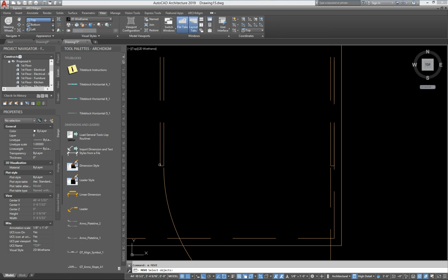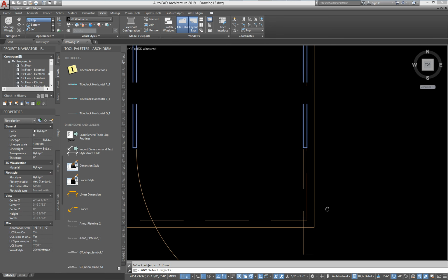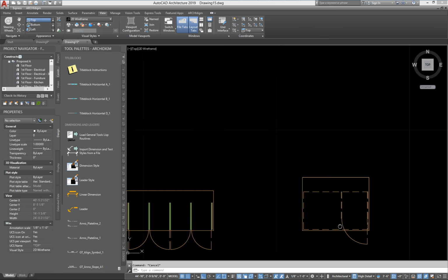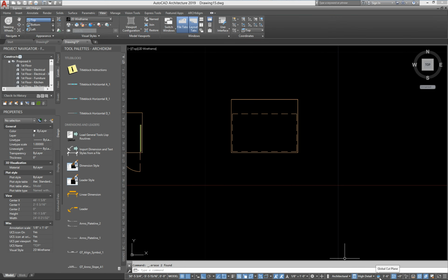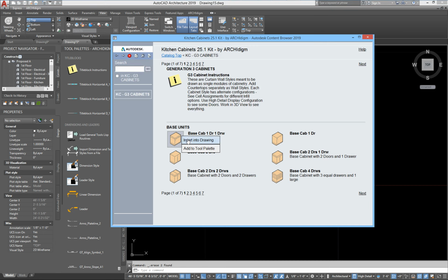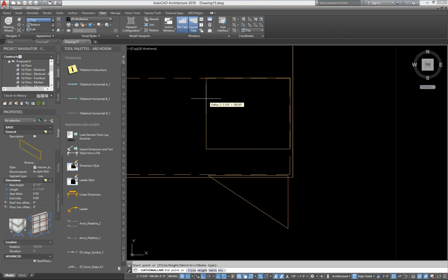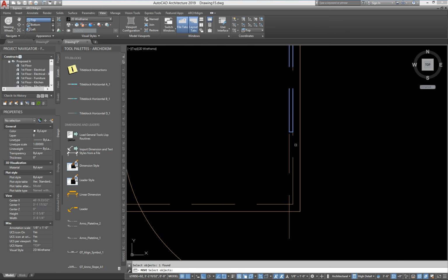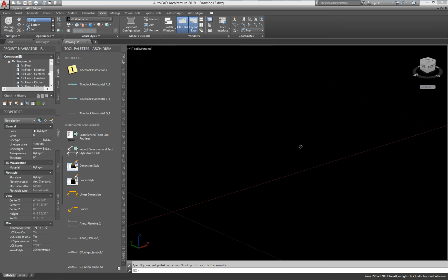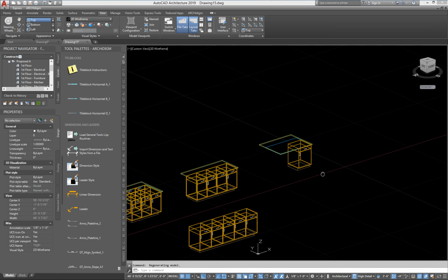I will now take that with my lock on. Oh, I drew that snapping again. Let's get rid of that. You got to be careful what I snap to here. So let's lock the Z. Good. All right. And then let's just draw that in here. I'll come over 24, and then I'll go ahead and just move that forward, this here to here. So if we look at that in 3D, that becomes one unit.